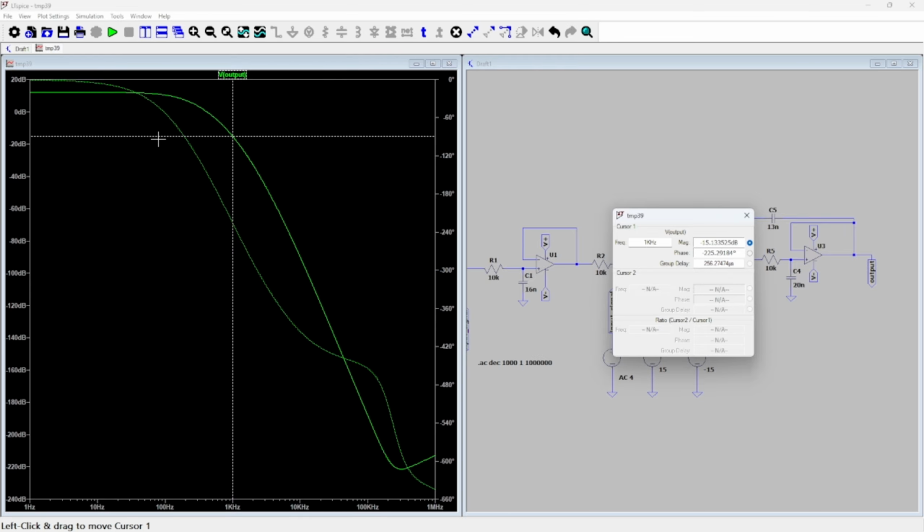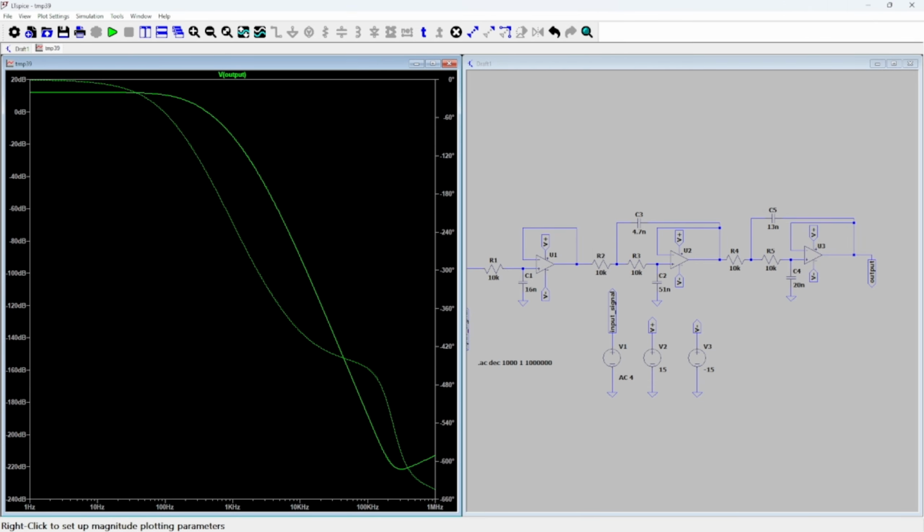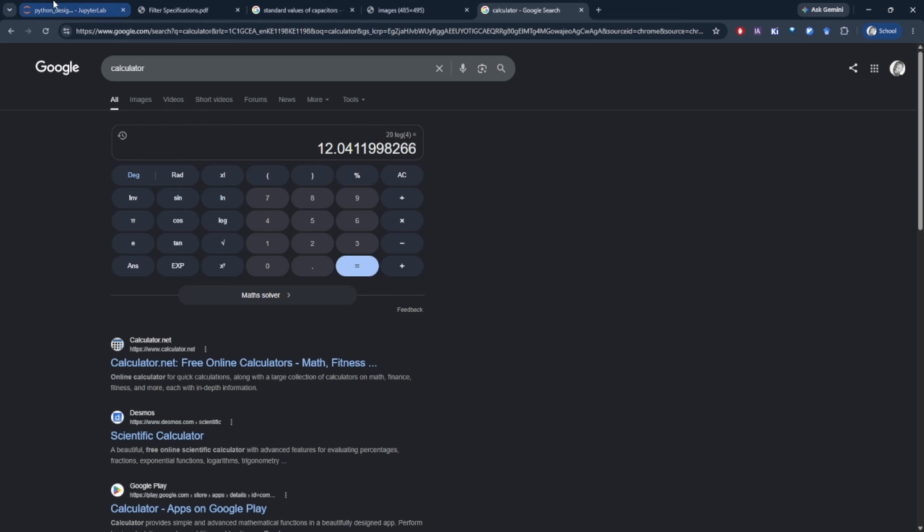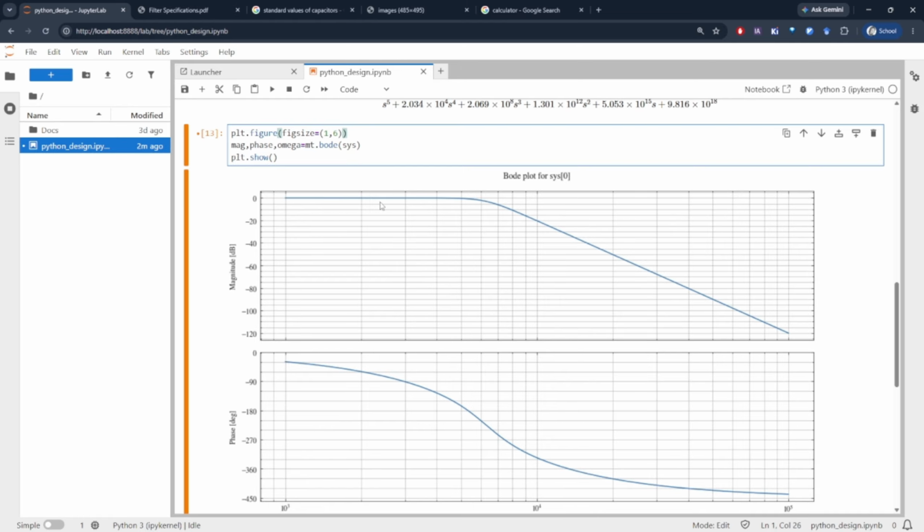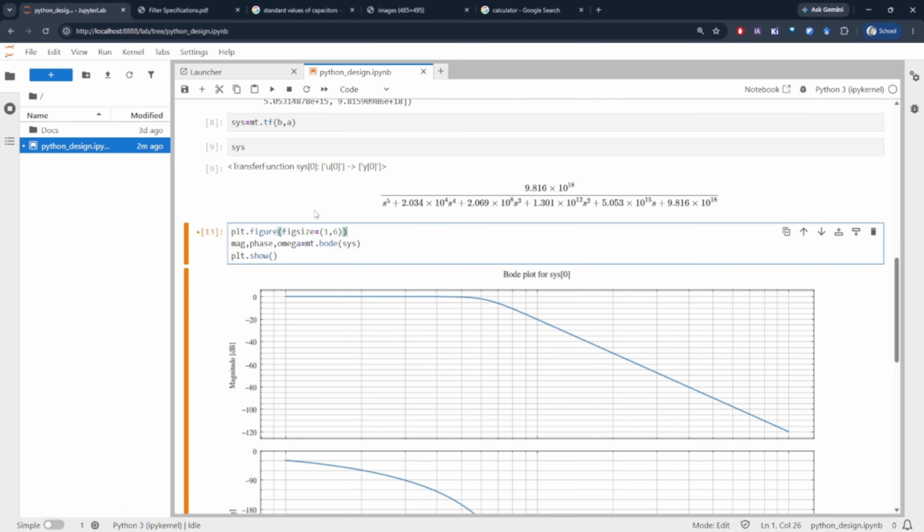If you look at this magnitude plot, you can see there's some similarity with our simulation. It's just flat until we hit somewhere here at 1 kilohertz. So in the next session, I'm going to show you how you can do this using MATLAB. Since you have already built it for LTspice, I'll show you how to use MATLAB and come up with this. So you spend less time doing this because it's easy and precise.